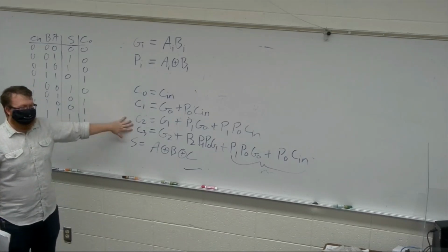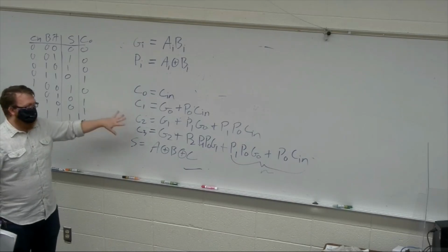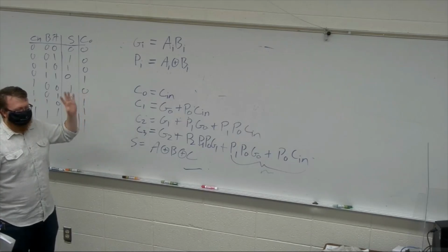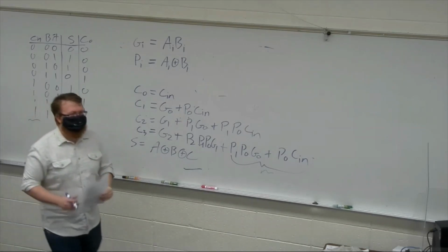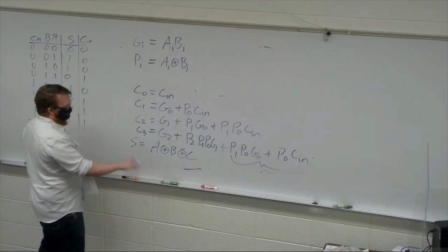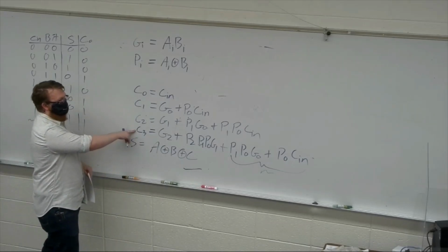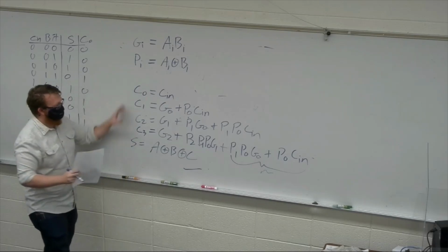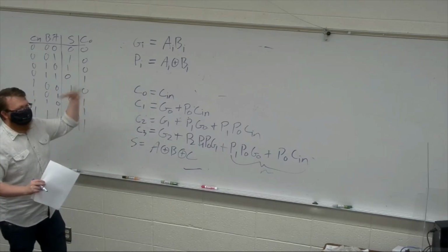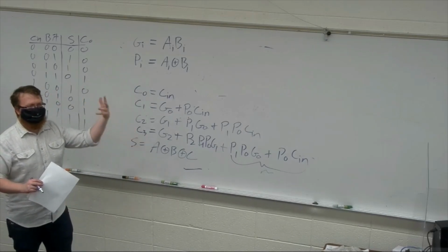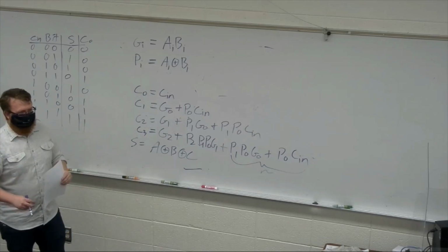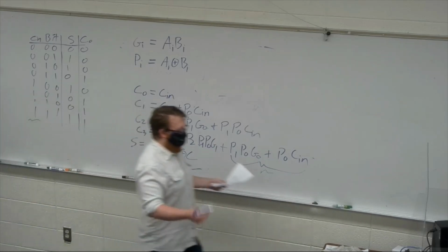But it is available in your book. The book spells it out explicitly. I'm deviating from the book to different notes because I did the notes. But really, you'd only ever look this equation up. I'm never going to expect you to memorize this equation. That's insane. But the takeaway is that I can just count these C's and skip ahead and not have to ripple them through, and then stitch them together and still have a better carry adder. So that's what a carry look-ahead adder is.